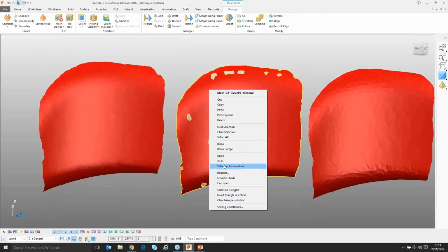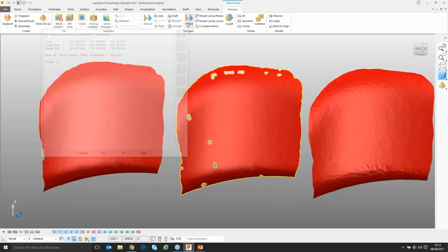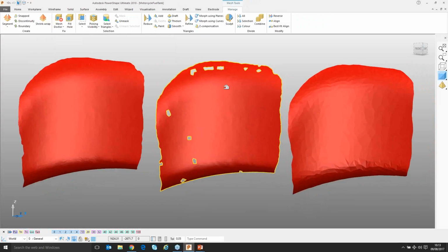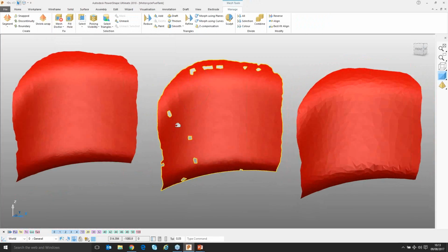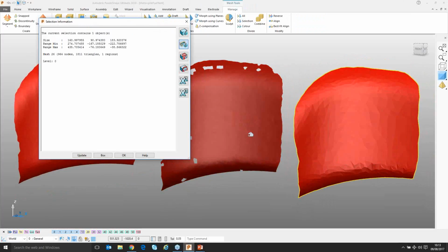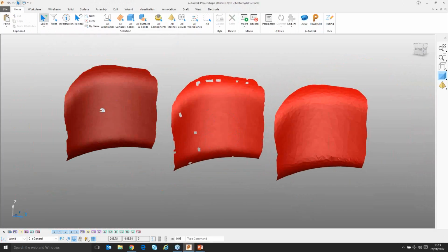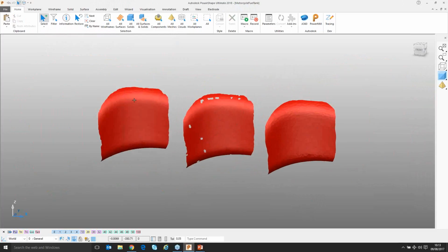The one where we've used really small values, 37,000 triangles. So getting off double the amount of data with no real improvement in the triangulation compared to the original one where we used the defaults, and that was 1,800 triangles. So there's always a trade-off, but the good balance point is where we've measured a few key sizes to get the numbers.